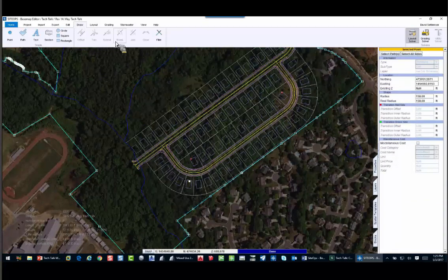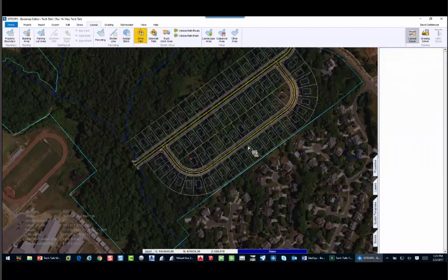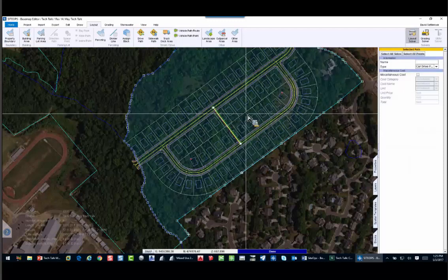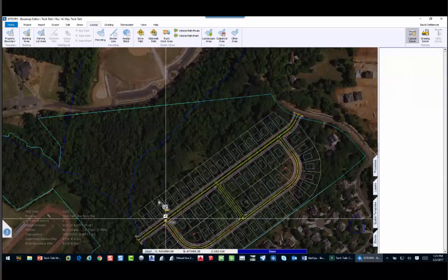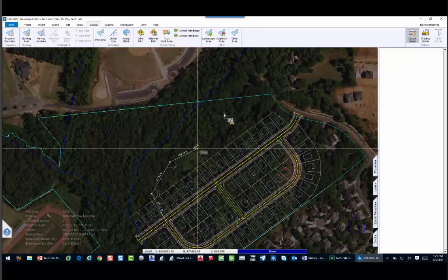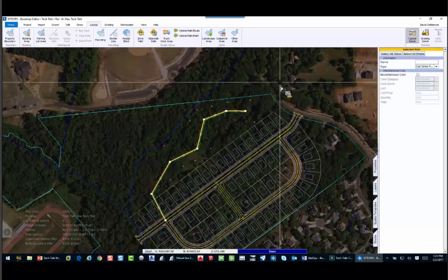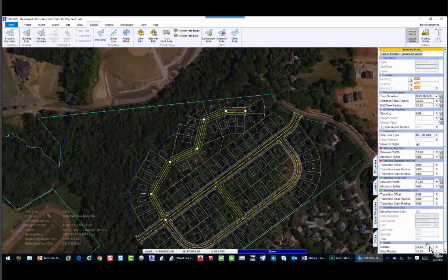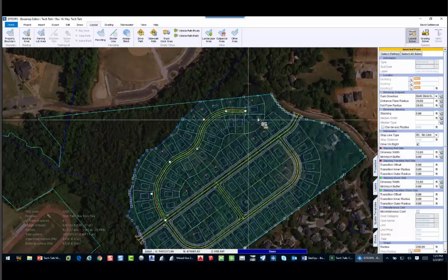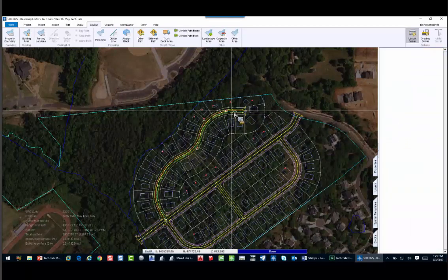I've quickly come in, and now at this point, it's also things like, I got to add more roadways, too long of a block length. Let's go perpendicular from one end to the other, do the midpoint. Again, however we want to draw this, I can quickly come in and do it. SiteOps can be creative. It's all up to your imagination as to what you want a subdivision to look like. It doesn't really care. I can come in and do something simple like this. Let's add some radiuses to it so it looks a little better. Let's just say 250. So the lots will start looking nicer, and I could put a cul-de-sac in. So got a lot of things you can do creative.